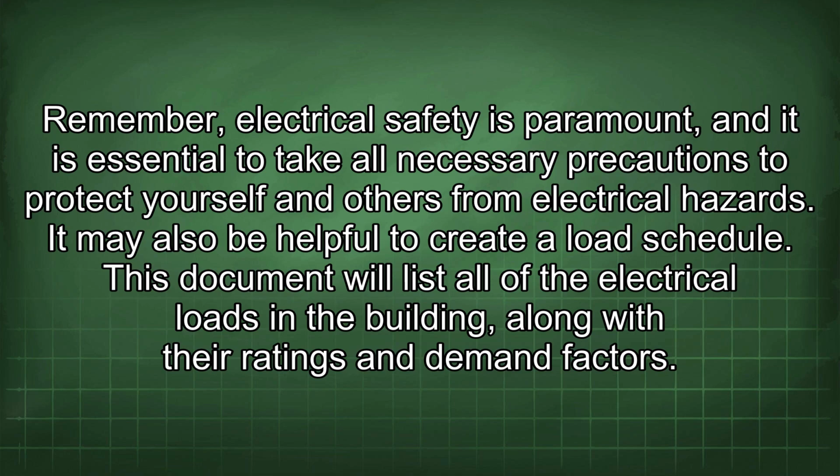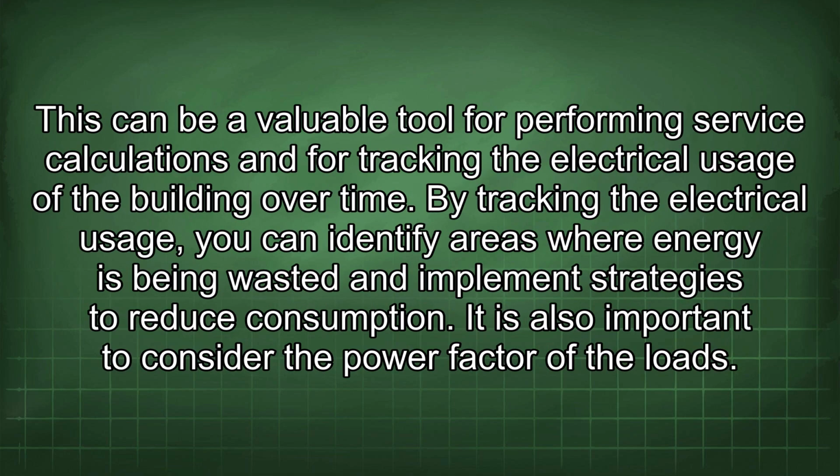It may also be helpful to create a load schedule. This document will list all of the electrical loads in the building along with their ratings and demand factors. This can be a valuable tool for performing service calculations and for tracking the electrical usage of the building over time. By tracking the electrical usage, you can identify areas where energy is being wasted and implement strategies to reduce consumption.